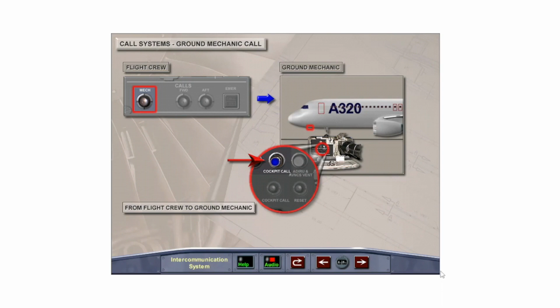When the push button is released, the horn stops, but the light remains illuminated. The light remains illuminated for 60 seconds, but it can be extinguished at any time by the reset button on the external power panel.